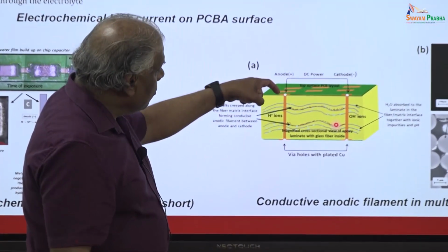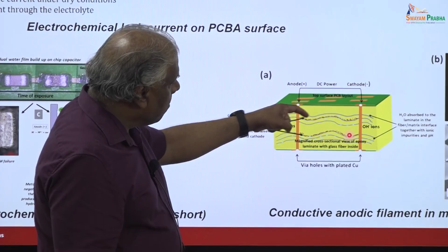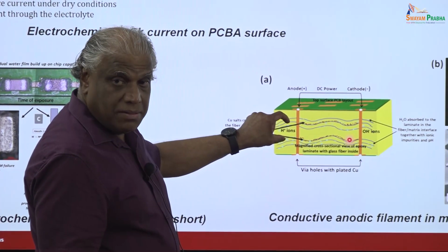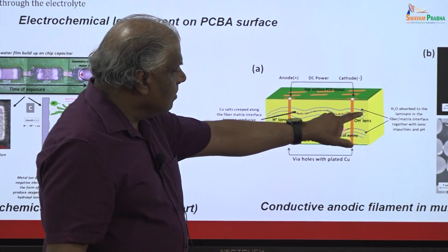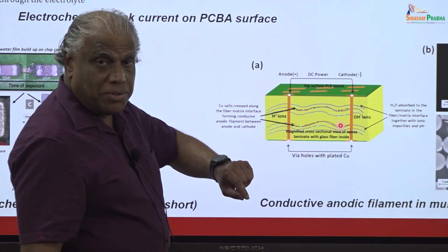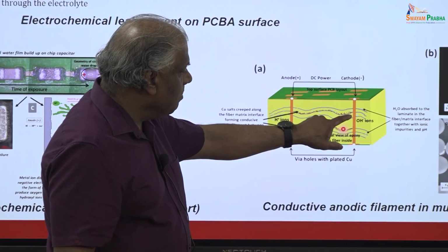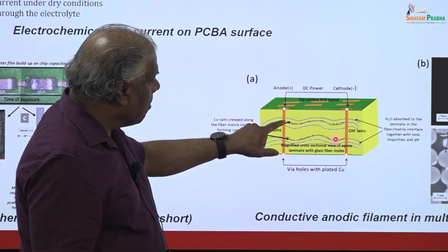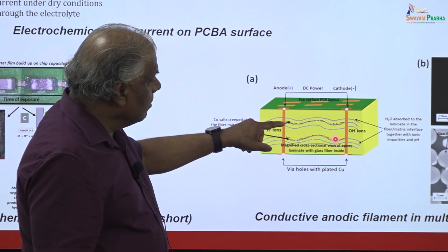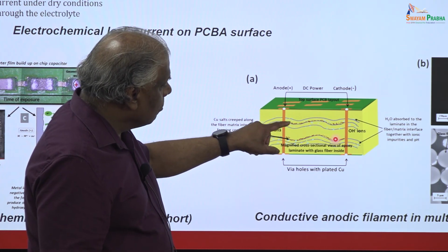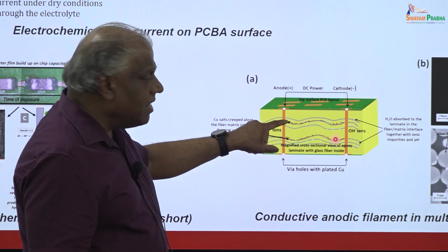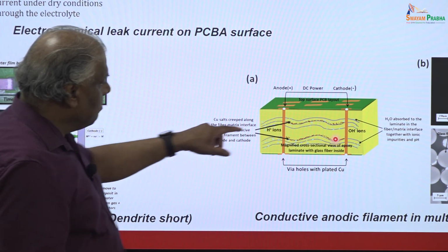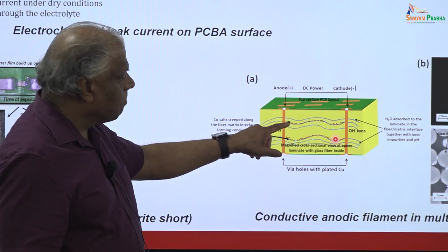So that means that when moisture is going in, there can be a copper wire sitting like this inside the laminate. This polymer is made of glass fiber composite, so there may be a glass fiber sitting like this. When this little moisture is corroding the copper, this copper product will be pushed. Since it is a very little water and it's inside the laminate, it will not form a dendrite, but it will immediately form some copper corrosion product.